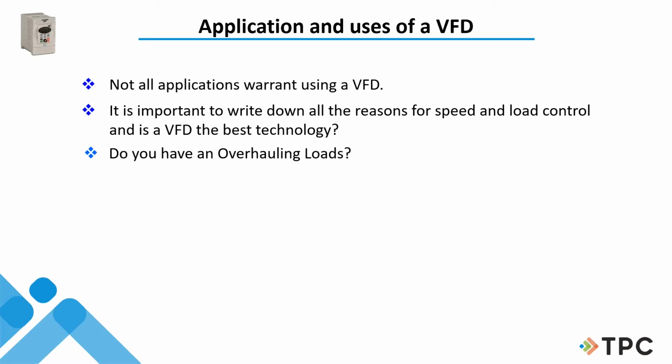Overhauling loads can be an issue. Not so much with cross-line motor starters, but when I put in a drive and I have a heavy load and I stop it, when it is told to stop, it doesn't stop right away. It coasts a little bit. When it coasts, it does what is called regen, and it regenerates voltage, and it goes into the back end of the drive, and the drive doesn't like that. So the drive will trip out. The drive will try to ramp it down, but if the load's too heavy, it won't.